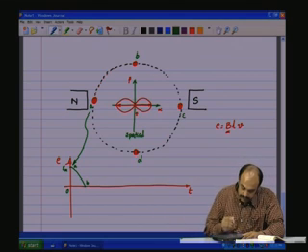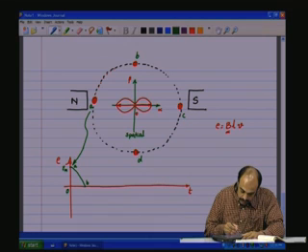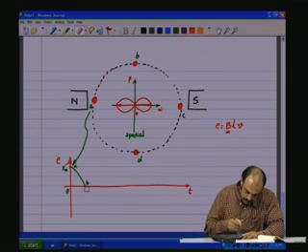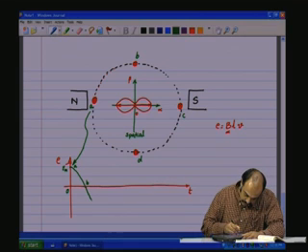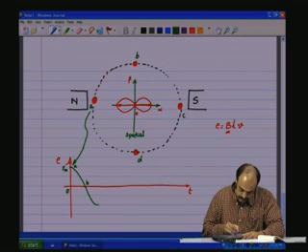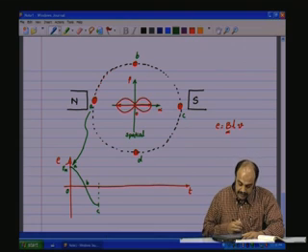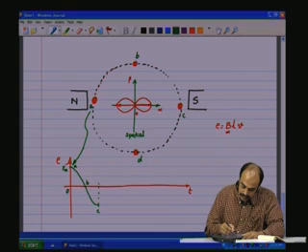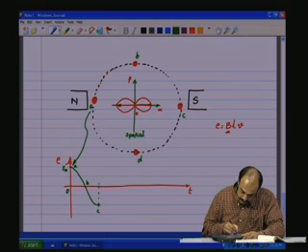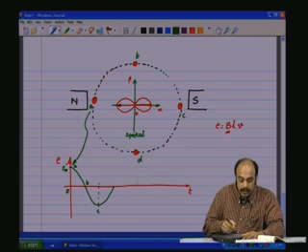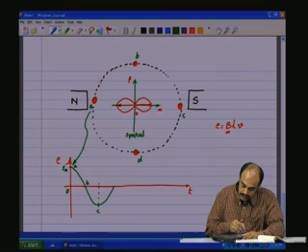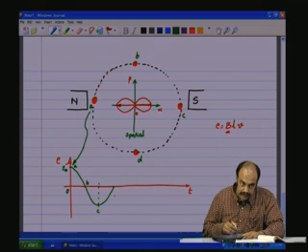So, from B to C, this is going negative. So, this starts going negative and reaches the maximum point C in the other direction, negative direction, that is here. And then from C to D, it again becomes 0 in the orthogonal axis orthogonal to the alpha axis, which is along the north-south pole direction.